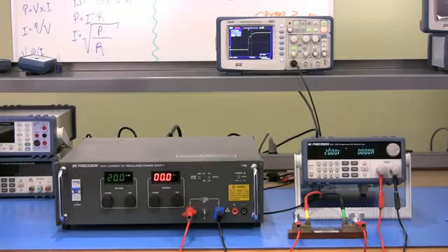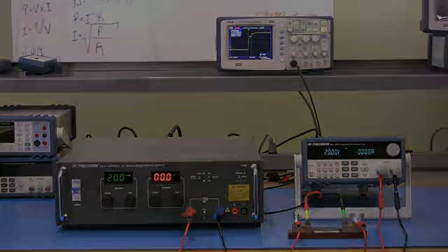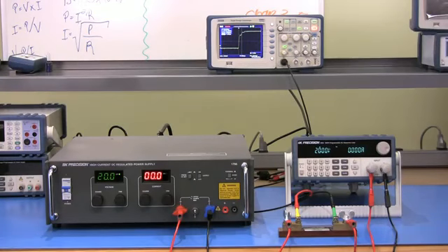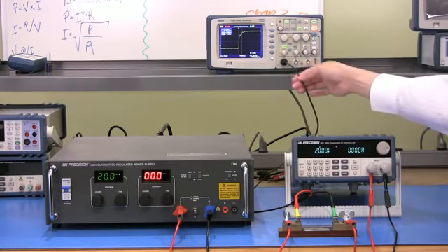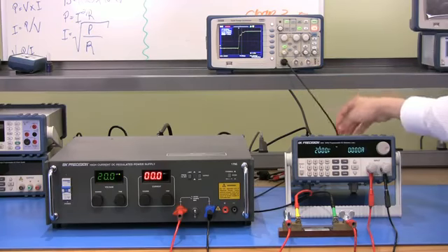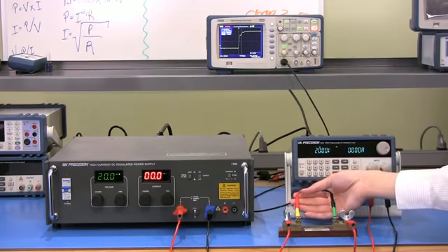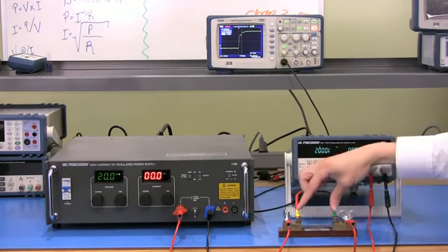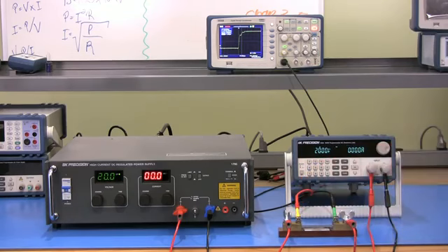For demonstration, I have a setup here to measure slew rate of a BK Precision 8502 DC electronic load. Here I have a BNC to banana plugs cable connected to a DSO, with the banana plugs connected to a shunt resistor rated for approximately 66 milliohms, 15 amps. If you are testing with higher current, use a larger shunt.